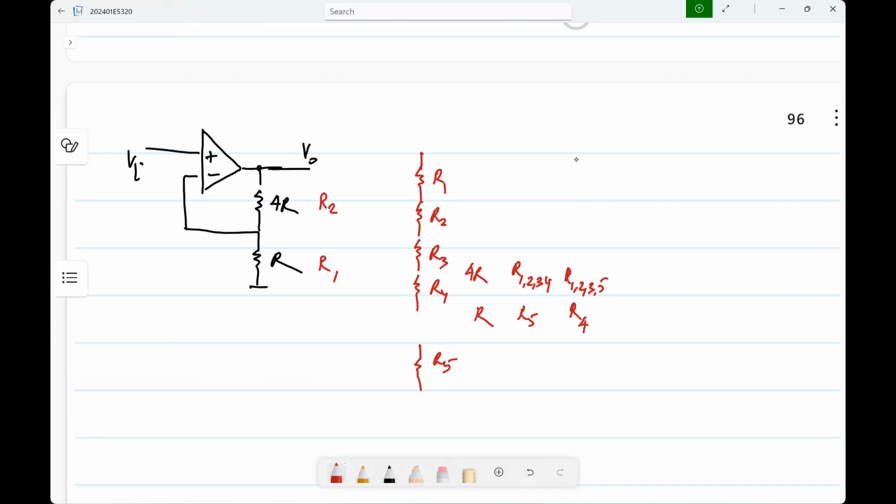and so on. But again, you will need a massive switching network here. Every resistor must be connected to some switching network. Obviously, when you do that, those switches should not be offering significant resistance, because then that will come into the picture. Those are all the practical details, but at least there is some technique that can potentially get rid of the mismatch.